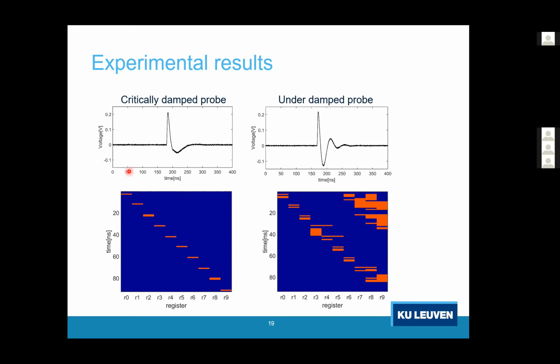If we play with the timing of this pulse, if we inject the pulse at the beginning, then we only fault loading into R1. If we inject the pulse 10 nanoseconds later, then we only hit R0, then we only hit R1, and so forth. So we're able to exactly hit the load to a single register, so we hit basically a single instruction.